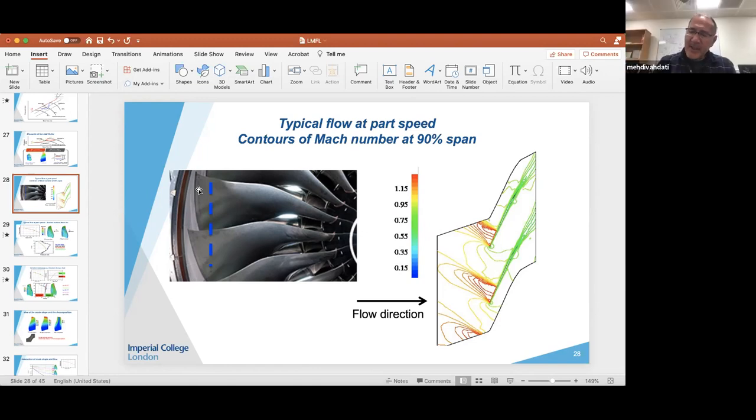Yeah, we do that because what we do, we put a phase lag boundary condition. So on the top and the bottom, they are at different phases, and so we use a phase lag boundary condition, and you can just do one passage. But when you do one passage, you can do one interblade phase lag or nodal diameter at each go.